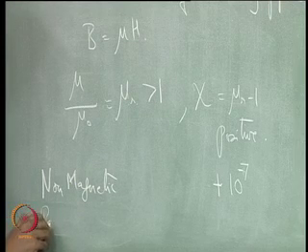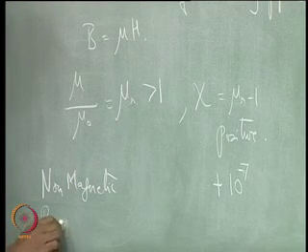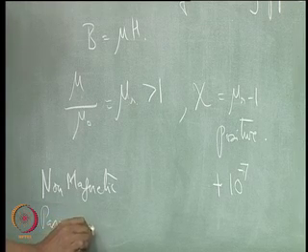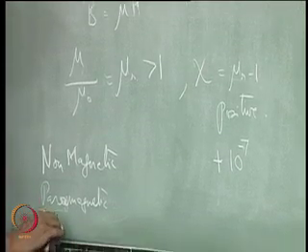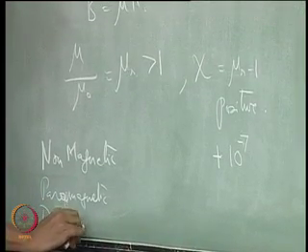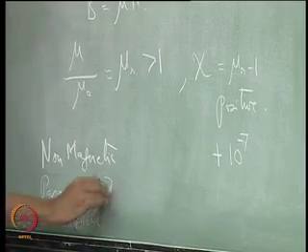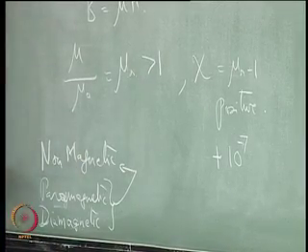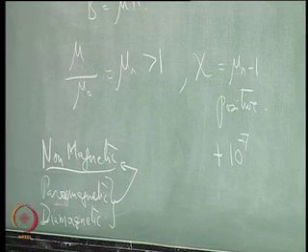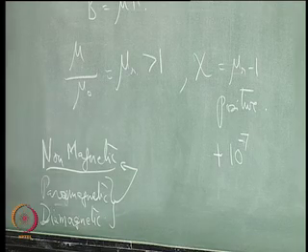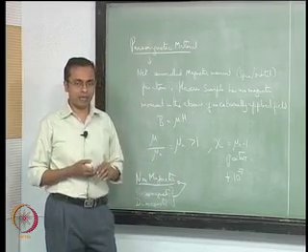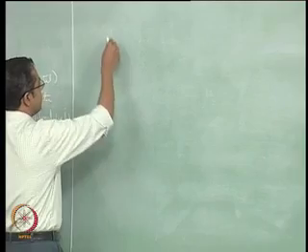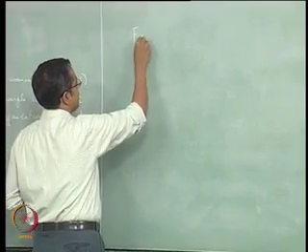Both para as well as diamagnetic, both of them are non-magnetic materials, because they do not have any magnetic induction left in them the moment you remove the externally applied field. So in terms of technological interest, they are not of great significance. The next type that we are interested in is the ferromagnetic material.